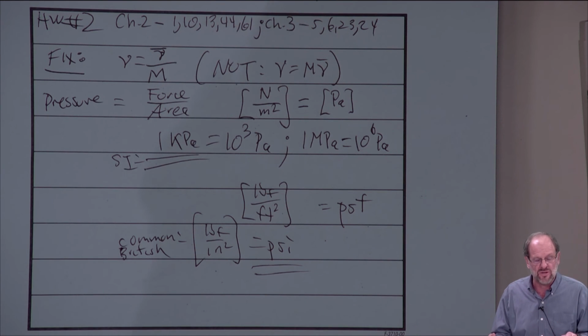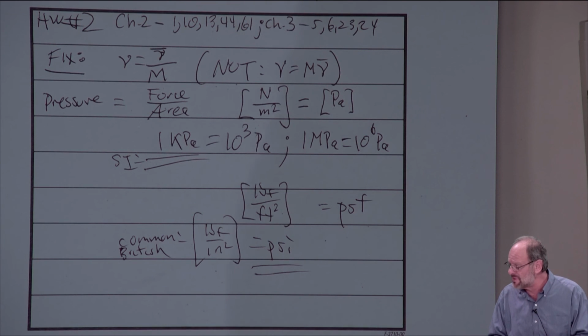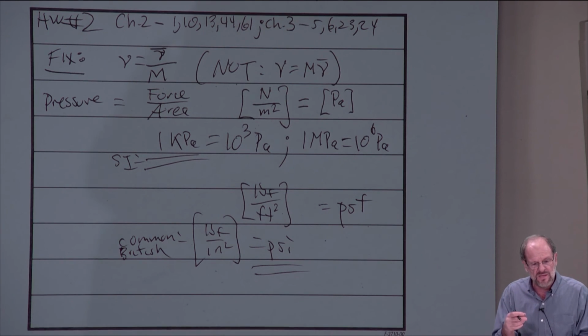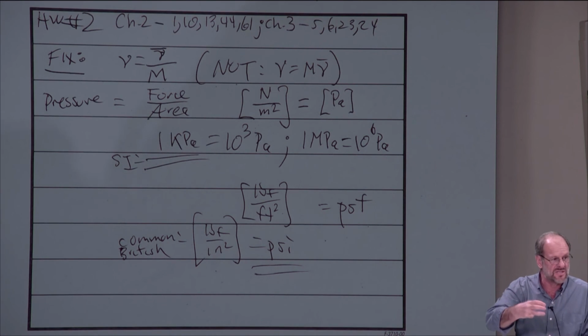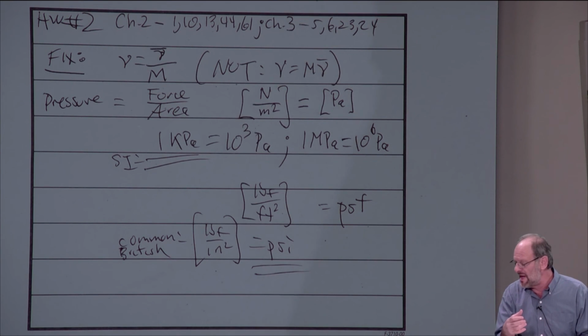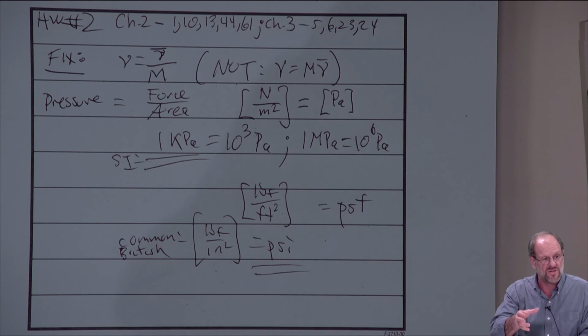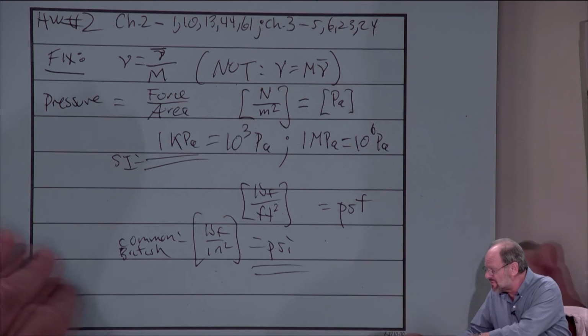The actual pressure is what we call the absolute pressure, or we can call it the actual pressure. But it's very common in industry and out there in the real world to take a pressure gauge and stick it onto our system, maybe it's a tank or a pipe or whatever, and then adjust that gauge to 0 so that the pressure on the pressure gauge would read 0. But that's clearly not the pressure. This is just a tool that's used. If you've zeroed your pressure gauge, then you're going to have to add the atmospheric pressure back on to whatever that gauge pressure says, and that's going to give you the actual pressure.